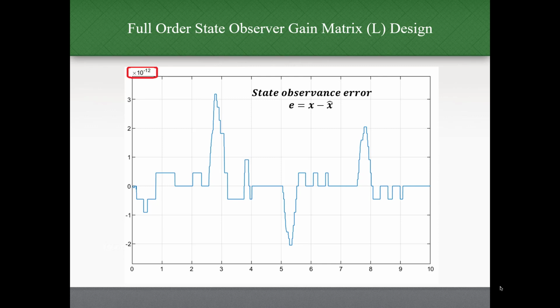So we designed and modeled a controller for our DC motor. We used pole placement. We designed an integral controller to track the input, and we also designed an observer for that model.